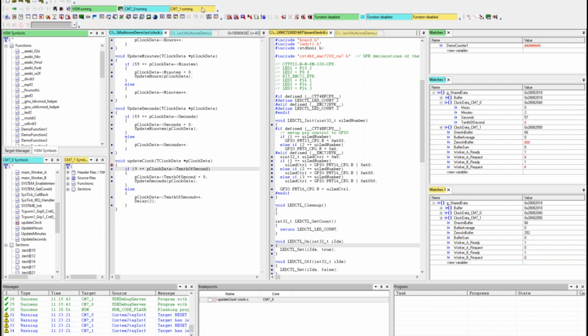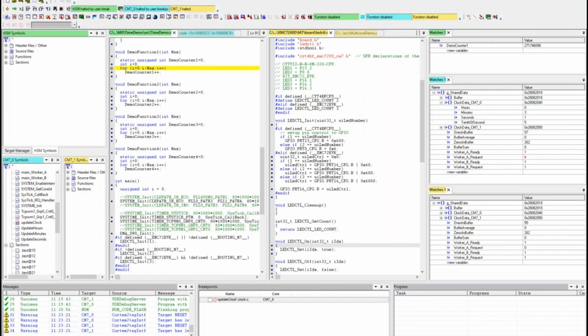started together synchronously, and we can now set a breakpoint again. Then you see we stop only in core 0 while the others kept running, and then we can disable the breakpoint. And if you want to put it back, everything, then we have to stop all the cores.